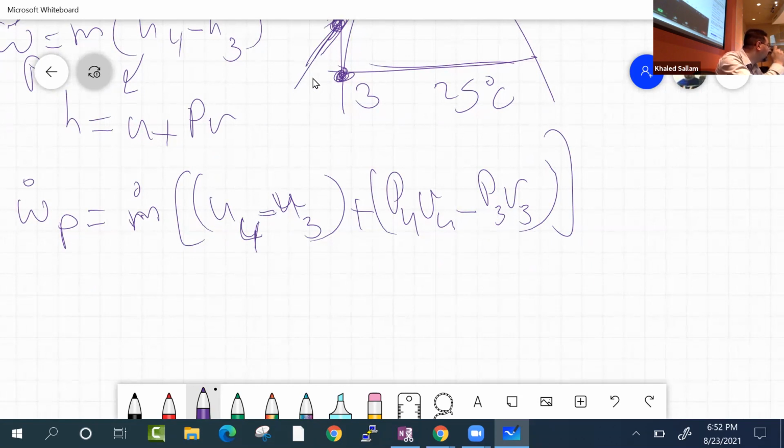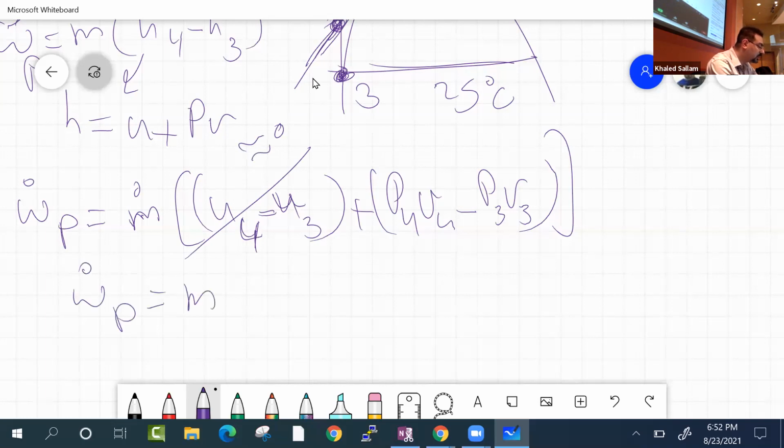Very little. I mean, yes, it gets hot, but again, those are the t-shirts and the shoes of Bill Gates. They are nothing compared to the change in enthalpy. So zero, almost zero. And so then the work pump can be approximated as PV minus PV.